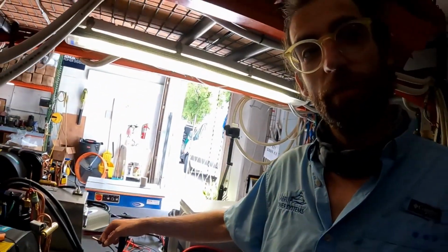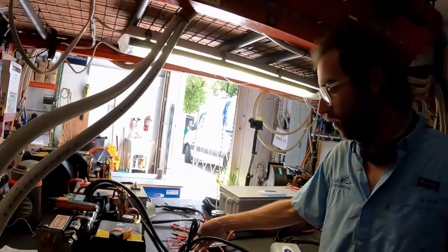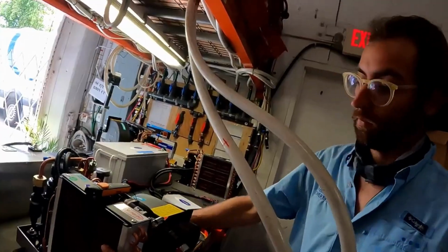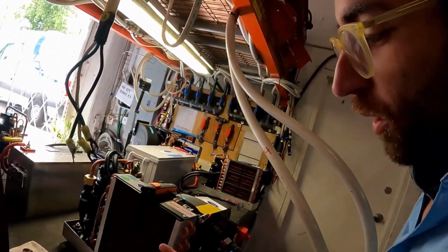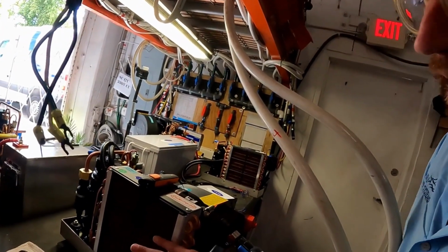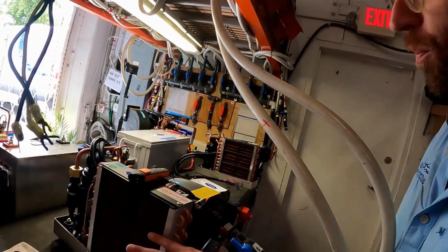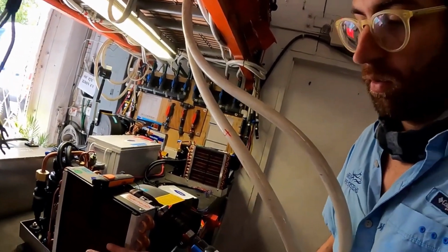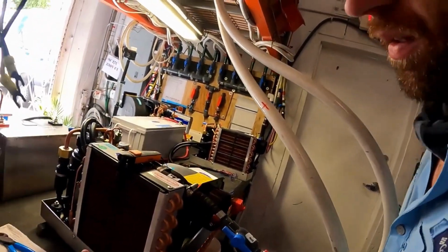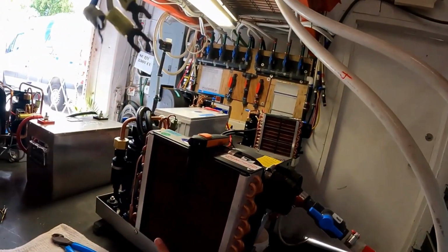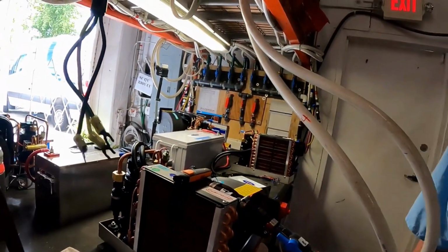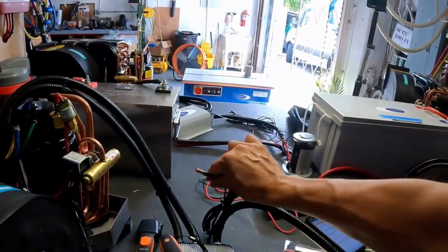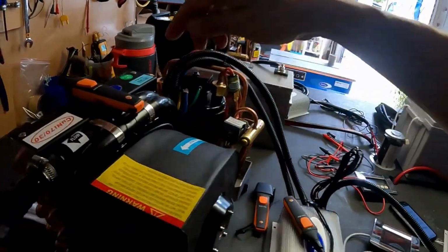Oh, the remote sensor. Where should it be located, Nico? So the remote sensor, we should really have this somewhere in the flow of the return. Exactly. Should be located here, no? We want to be very careful how we place it here, and make sure the metal bulb aspect of it is not touching the metal. Not touching the metal, a little separated, no? We can put a plastic here. Or exactly. Sometimes you'll have a return vent. Let me grab a return vent. I'll show you that. That's the sensor. And this is the sensor that should be located here.